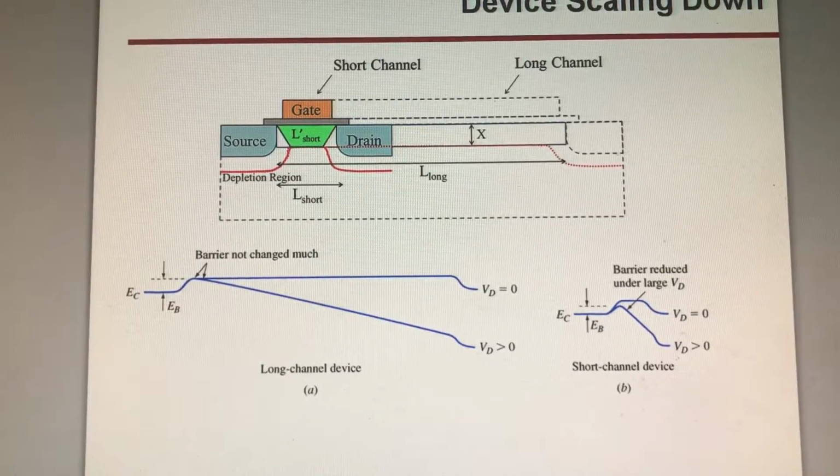All of this causes leakage current, which in turn can degrade the performance of the device or slow down its operation. So we have to fix these problems and continue to supplement them. To better handle the gate control, the process of bonding gate, oxide, source, and drain continues to evolve, and now we are developing a vertical structure using FinFET.